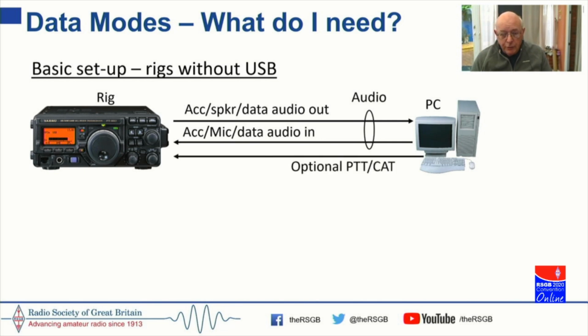The other thing that you might like to add is computer control of your rig, so you can change frequency and transmit and receive, etc. The reason I say that that is useful is because most data mode software have got computer control facilities in them, so you can actually run the rig as well as the data modes from within the data modes program.